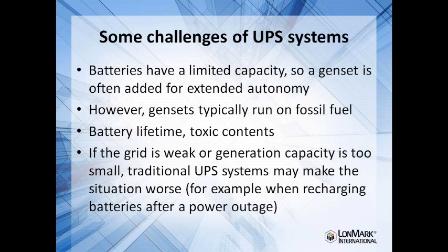An example is when the power outage is over, then if everyone wants to recharge their batteries in their UPS systems, this creates an even larger load than you had before on the grid. So instead of supporting the grid, these systems can actually bring the grid down again.